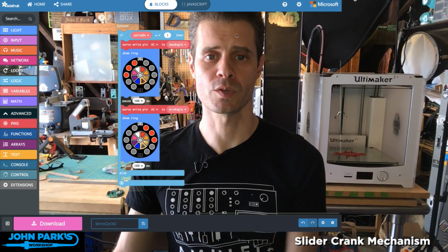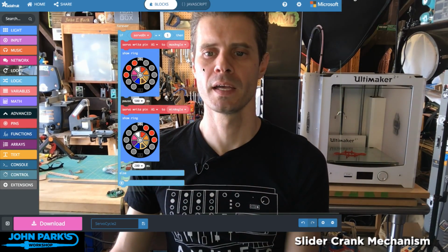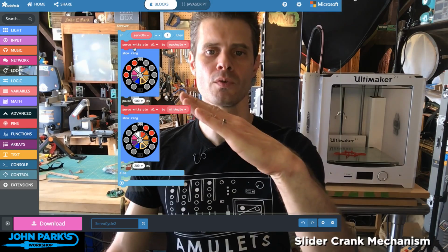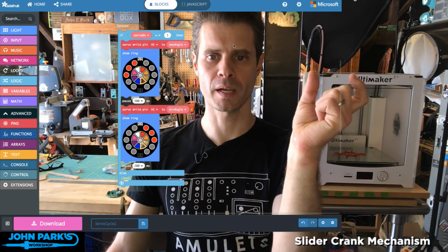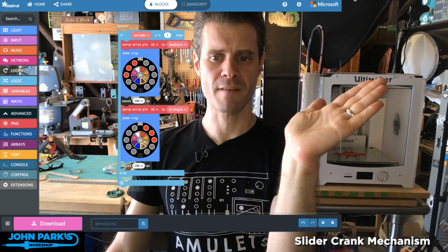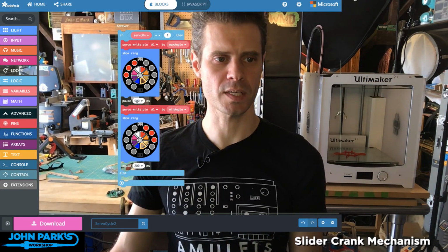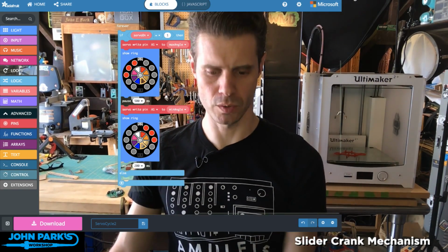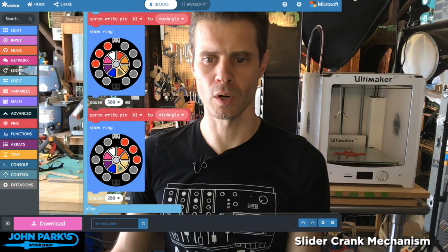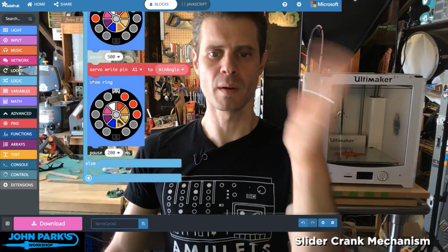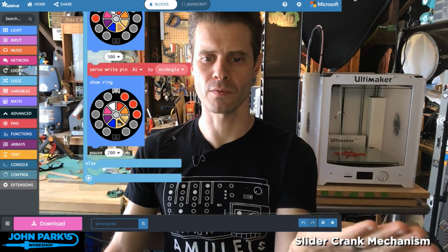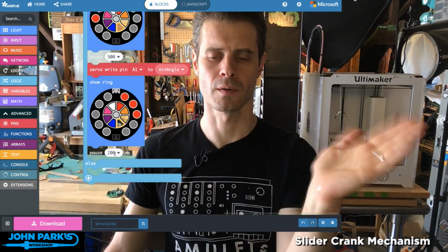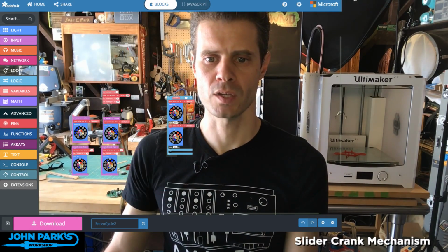When it is, which means I've switched that little switch to the right, then we're going to move the servo to its maximum angle. We're going to show that color ring as red. We're going to pause half a second. So that's this pause 500 milliseconds right here. Then I can zoom in. Then we're going to go to the minimum angle, set the color lights in the other direction, and I'm pausing for 200 milliseconds. So it's an uneven motion or uneven timing. Okay, so that is it.